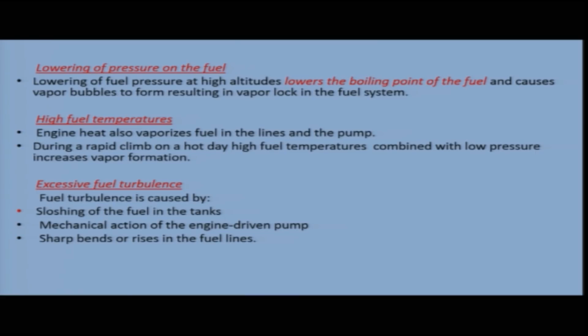Because of high fuel temperature, engine heat also vaporizes fuel in the lines and the pumps. During a rapid climb on a hot day, high fuel temperature combined with low pressure increases vapor formation. You have high fuel temperature, and since it is a rapid climb, you encounter low pressure also. This low pressure combined with high fuel temperature forms vapors.